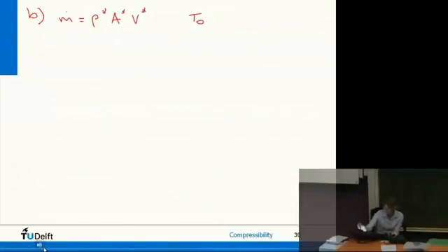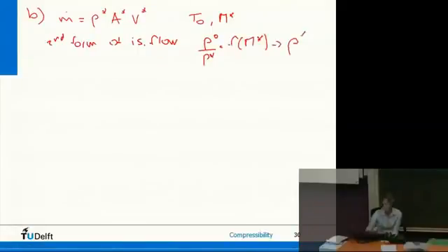So we have T0, we have Mach at the throat. So we can use the second form of isentropic flow relations. Rho 0 over rho star is a function of Mach star, and that gives us rho star. Yeah? V star. Any ideas on the velocity in the throat? Yes? Find the Mach number throat, V star over A star.